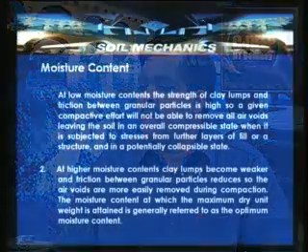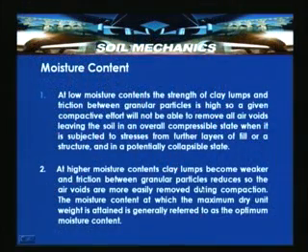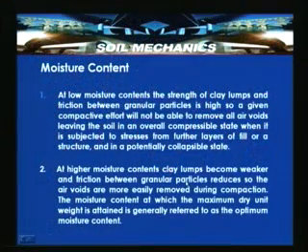Secondly, we have seen low moisture content. Now, let us look at what will happen at high moisture contents. At high moisture contents, clay lumps become weaker because they become softened, and the bonds between the clay lumps weaken. In the process, the friction between the granular particles is reduced. So, the air voids are more effectively and more easily removed during compaction, so that a dense matrix can be achieved.